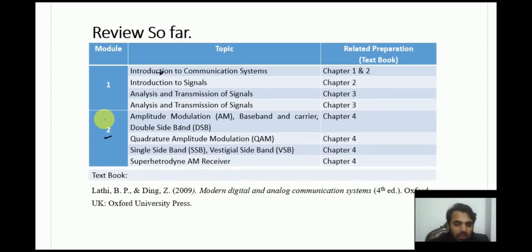In amplitude modulation, in this module 2, we talked about DSB-SC signals, that is, double sideband suppressed carrier. We don't send the reference signal in the transmitted signal. So on the receiver side, the circuitry would be a little bit complex. You would need a local oscillator which is in sync with the transmitter, with the transmit modulator. So that is basically the downside of it.